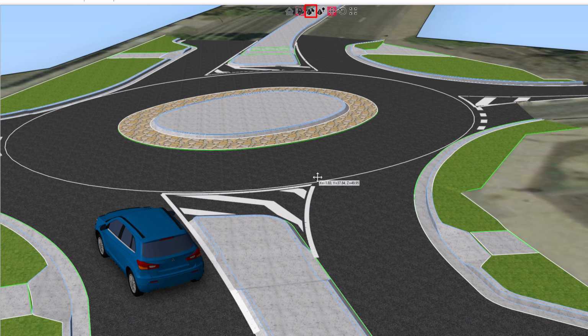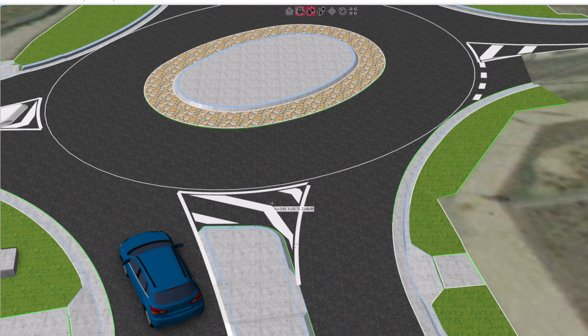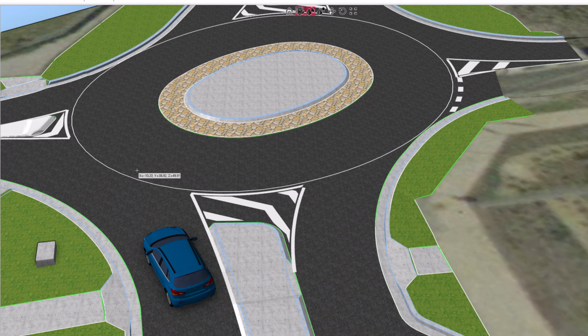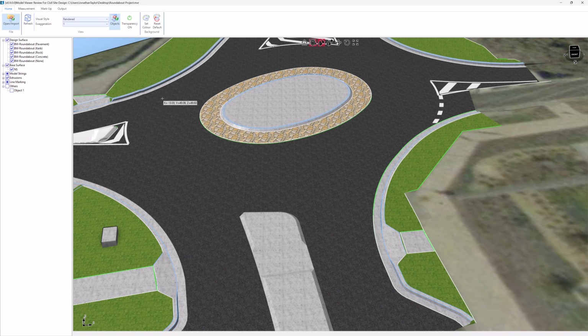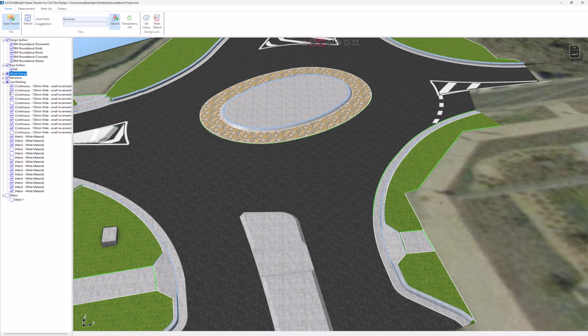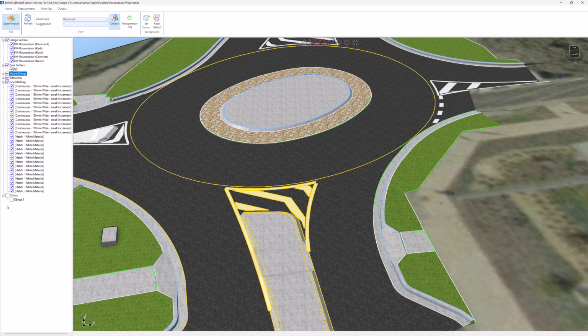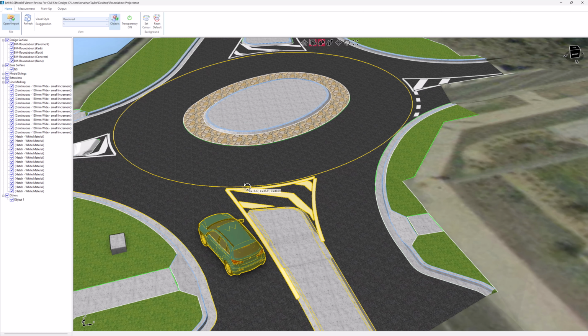If you need to select objects from screen, you do that using this particular button found on the toolbar on the top of the interface. So we click this button, and then all you would need to do is to drag a rectangular window over the area that you want to remove from the view, which in this case is this area here. All those objects are then highlighted, and then we would simply use this button here, which is the one with the light bulb, to hide these objects from the display. If you want to turn them back on again, you'd very simply come into the objects list and check them on individually, or as I'm going to do now, I'm simply going to check on the whole group to ensure that they're all being displayed. If at any point you've got content selected on screen, you no longer want that selected, just press Escape.